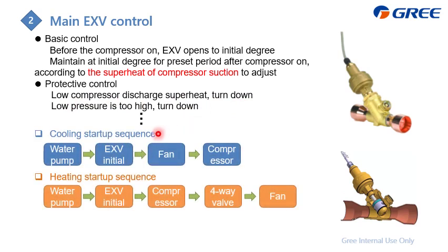And here is a summary of the startup sequence. For cooling, first we will turn on the water pump. After that, make the EXV do its initial opening. After that is the fan, and last is the compressor. And here is the cooling, and this is the heating.